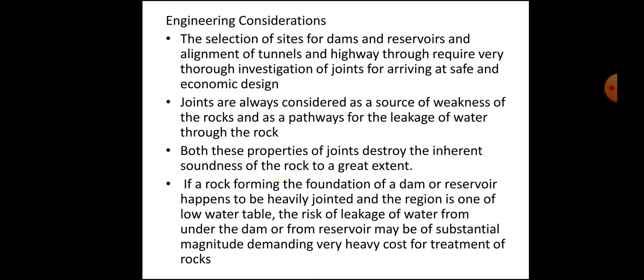Engineering considerations. The selection of sites for dams and reservoirs and alignment of tunnels and highways require very careful investigation of joints for arriving at safe and economic design. Joints are always considered as a source of weakness of the rock and as pathways for the leakage of water through the rock. Both these properties of joints destroy the inherent soundness of the rock to a great extent.